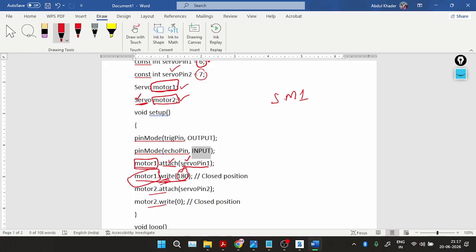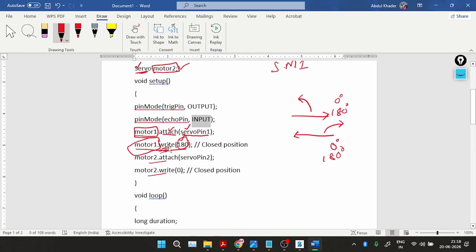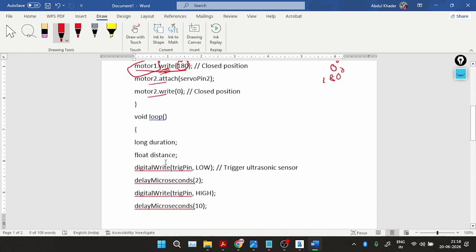See here, you might have observed the angle 180 degrees and 0 degrees. Initially, if you observe, both the gates will be on a flat horizon, but when you see the directions, they both will be different. So you can call this 0 degrees and this one 180 degrees, or the reverse. That is completely your wish, but both have to stay opposite, because one gate will open counterclockwise whereas the other will open clockwise. Okay, so that's why I have kept both the gates in opposite directions.